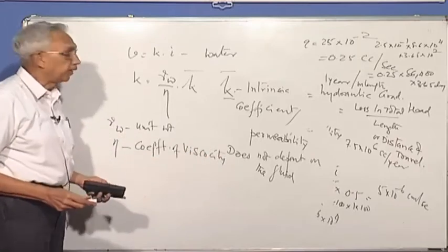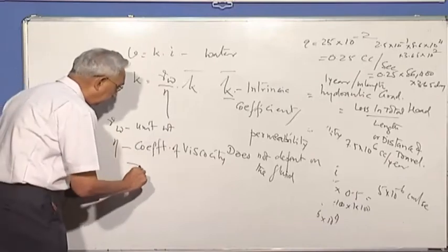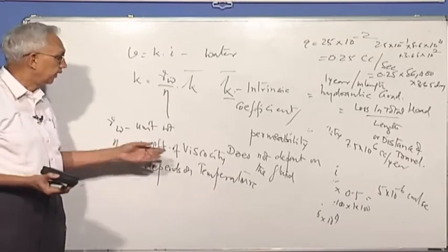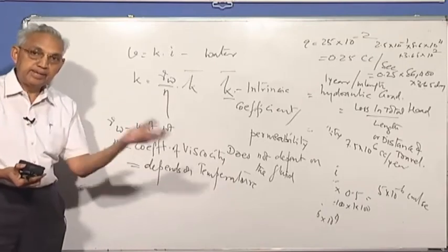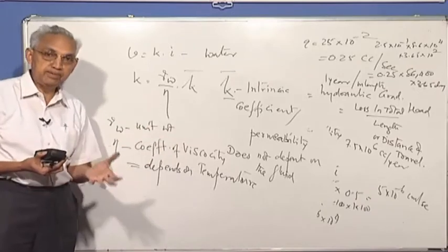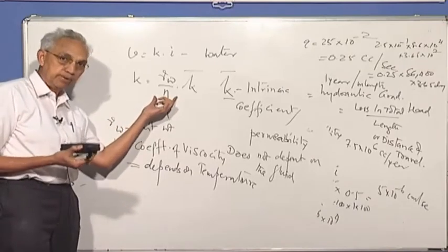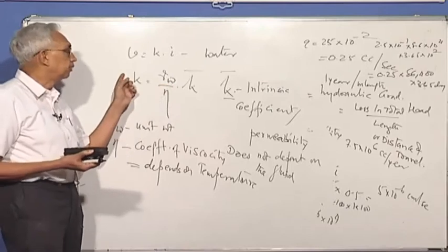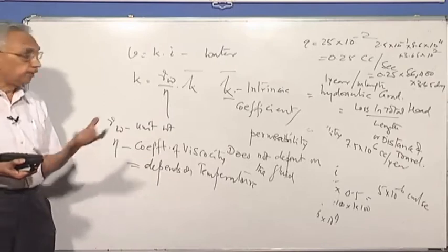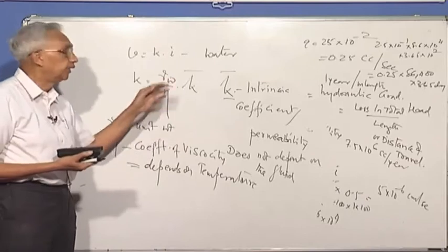That's another important parameter. Is the coefficient of viscosity the same or does it depend on temperature? You know that when a fluid is heated, the coefficient of viscosity decreases and it can flow faster. So please remember that we have this problem even in soils. If you have a cold temperature, the coefficient of viscosity of water is low, and then the coefficient of permeability can be high.